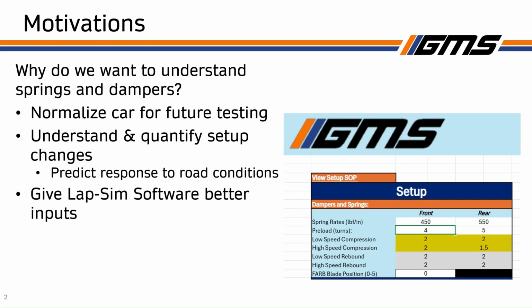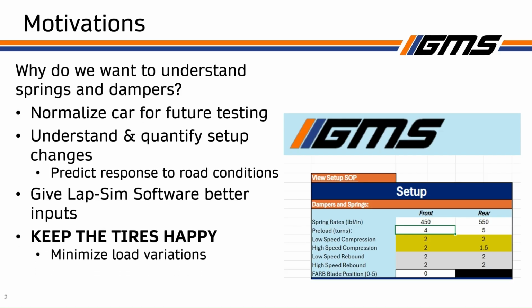Another thing, for teams that have access to lap sim software: if you can understand how the springs and dampers are going to work during the design phase, and design them to be pretty close to an ideal setup before you even get into the lap sim software, you're going to have a lot better time and get a lot better results out of it. But I think the biggest reason that you want to understand them is to keep the tires happy. The tires are the only thing between you and the road. And if you can minimize the amount of load variations happening to the tires, you're going to get the most grip, and the car is going to be the most controllable and predictable for the driver.